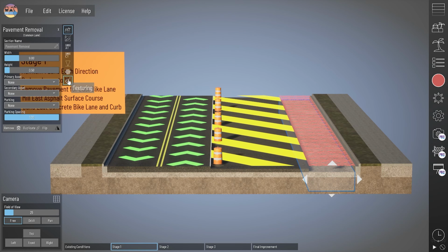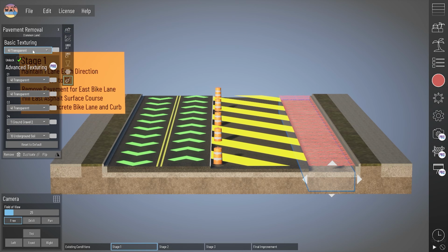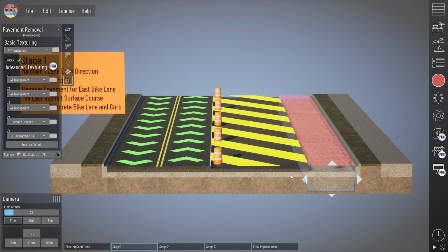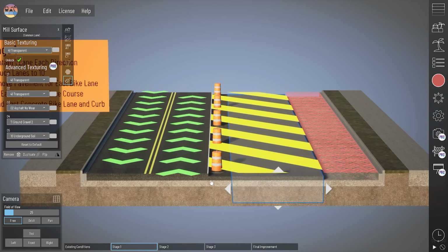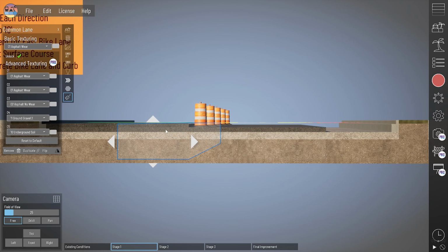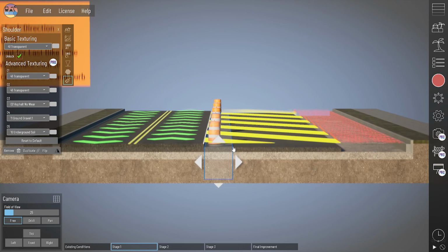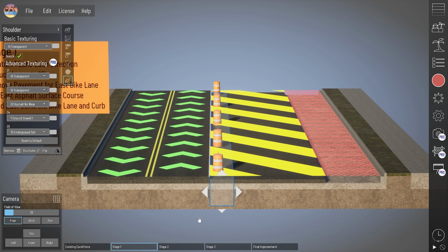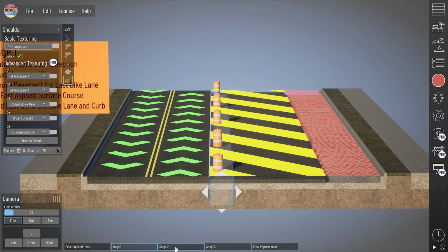See, I've used some of our texture abilities for pro users to make certain layers of that pavement section transparent, and also showing a milled surface. So you'll see I've got 2 layers of asphalt for my road. That way I can turn off that top layer to show a milled surface for those middle lanes that we would want to keep the most of that asphalt for.